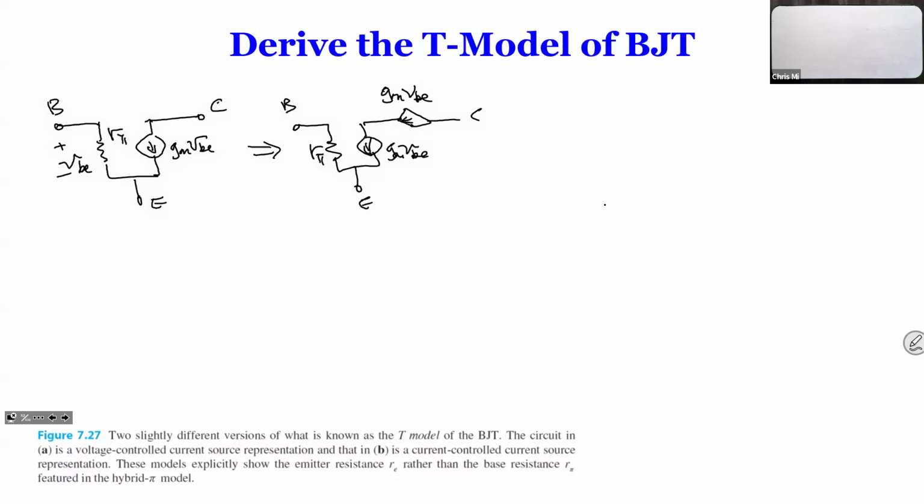As we said before, if you add a current source onto that branch, it doesn't change mathematically. I mean, even physically, you can do that. You can add a couple of current sources as long as they have the same current. You cannot have current sources in series if they don't have the same current. You can have them in parallel, but not in series. They have to be exactly the same amount of current.